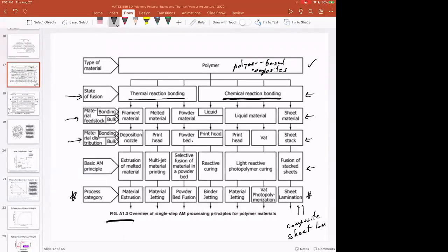It's not called stereolithography, it's called vat photopolymerization, and it's not called fused filament fabrication or FDM, it's called material extrusion. So make sure that you're using some of this standard nomenclature so we're all on the same page, because different companies will call their processes brand names or different things. That's just more of a branding or industrial exercise. We want to talk about the scientific and engineering basis for what's going on and try and leave the hype to people who get paid to hype things.